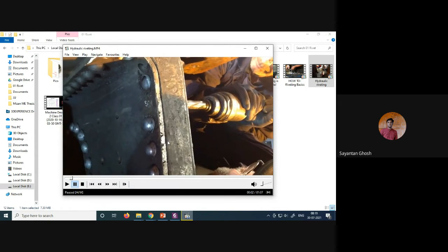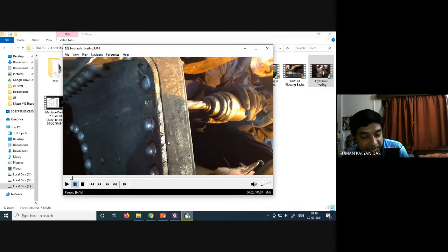If you are dealing with finer grains, that actually enhances the strength of the material, rather than having a coarse grain structure. Those types of welding process that I was just referring to promote that fine grained structure in the material, and hence it is found that the joint is stronger than the parent material. That's why, due to this development in welding technology, they are now gradually replacing the riveting process.